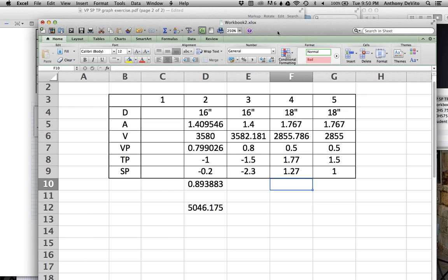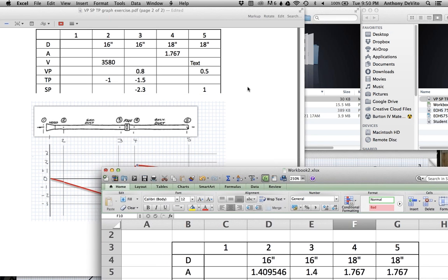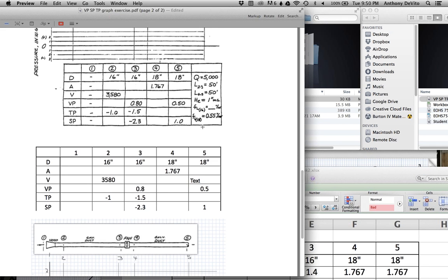Now normally when we design the ductwork, we would estimate how much the loss is using K for that ductwork. So if it's galvanized iron ductwork of a certain diameter, we would use K equal to 0.013, let's say, and we multiply it by the number of feet of ductwork. In this case, they gave us a summary factor. They told us that for 18-inch duct, the loss of static pressure is equal to 0.55 inches per 100 feet, it looks like. I hope I'm reading that correctly.